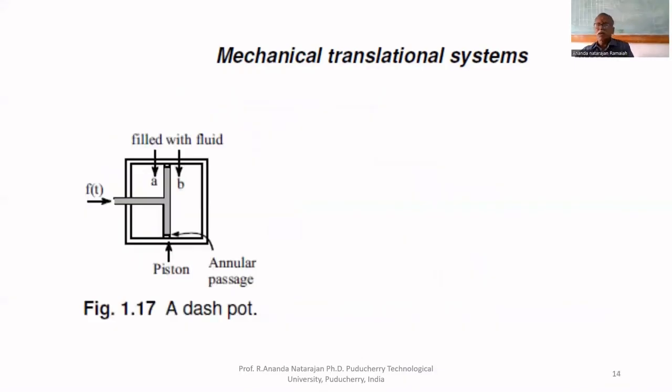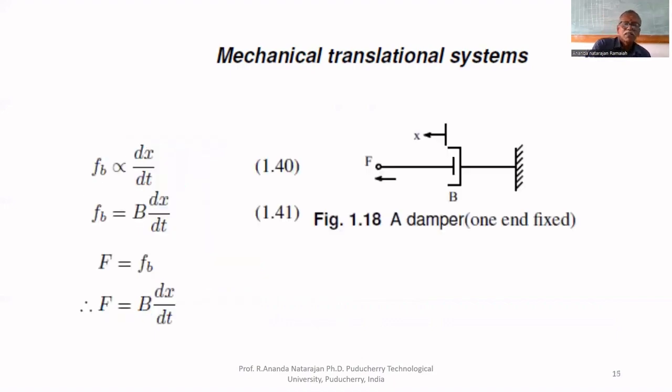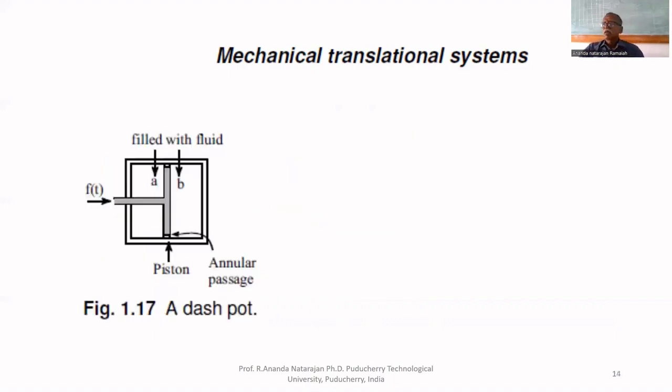The second case is the dashpot. The dashpot is a basic property of a mechanical structure, but this can be understood by this example. Dashpot means, suppose I don't want something to vibrate and then settle when I leave it. It should go slowly and reach its position, like our door closure. In that case, what they will do is put a piston here.